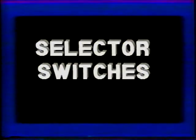Selector switches come in 3 types, and each type has 2 styles. The 3 basic types are 2, 3, and 4 position switches. These devices have either a 4 or 5 port arrangement. The 2 styles of each type either block or exhaust the unused ports.